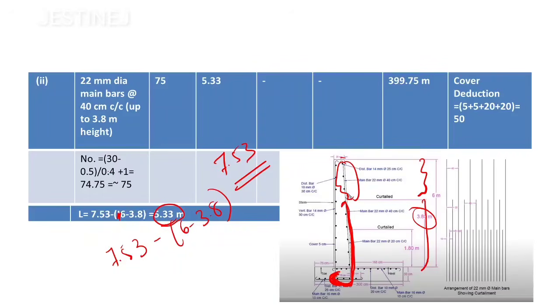And then you can calculate the total number of bars by the equation. The bars are arranged in this way, and we are providing these bars 20 centimeter to this side, and here also 20 centimeter to this side. That is not actually clear cover, it is the distance which you have to provide.